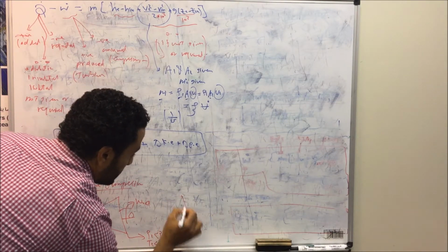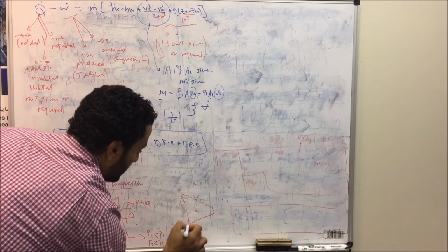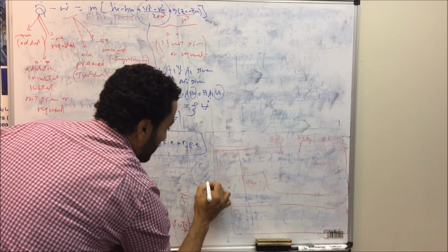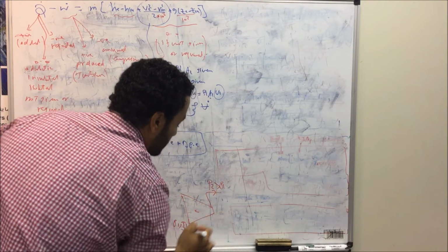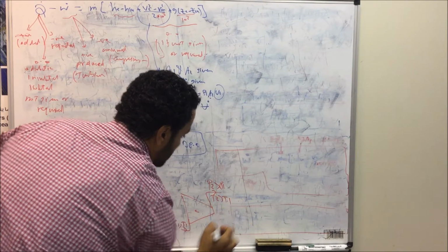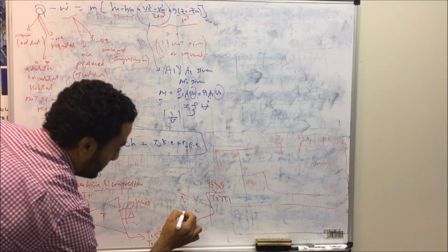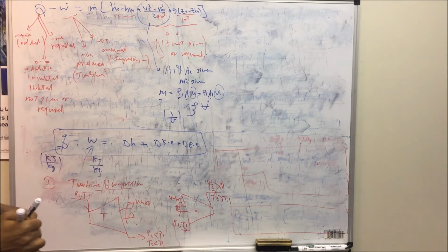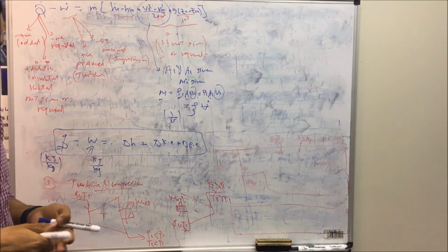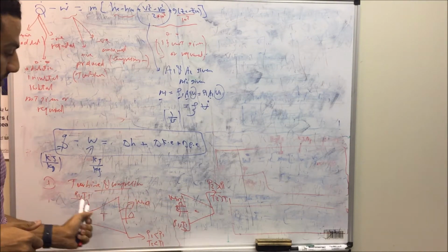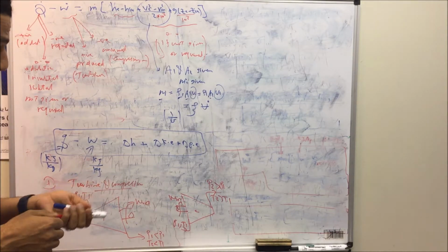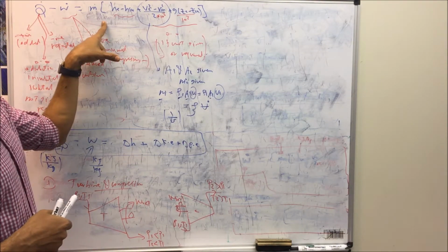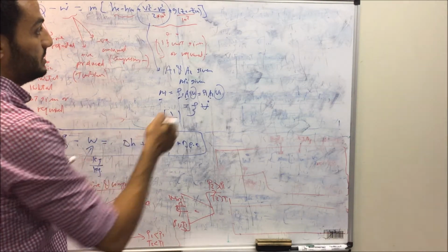The reverse of this actually is the compressor. The flow comes to the compressor at low pressure P1, low temperature T1, and the function of the compressor is to increase the pressure, and as a result the temperature will also increase. Based on that, the compressor consumes work. So we have input work to the compressor. In those two cases, we have a single stream at inlet and a single stream at outlet. So we can just apply this equation, which is the first law of thermodynamics for an open system, single stream.